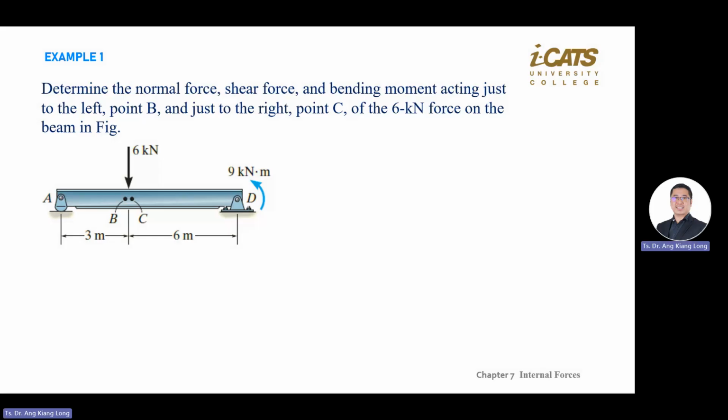Okay, what are the external forces at A and D? First step, solve the external forces first. It means you draw the body, copy the external force given, and find the reaction at A and D first. So refer to the diagram that I gave you.